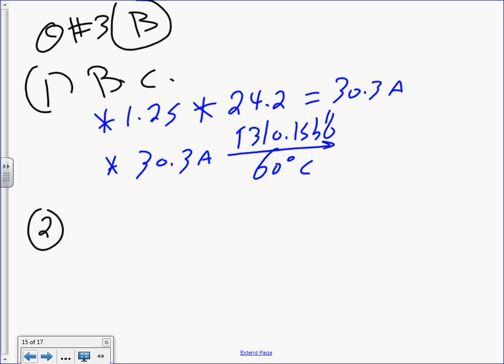The code allows you, guys, if it's 0.3 or less, you can get rid of it. So really, for all practical reasons, since the amps here is very small, this becomes 30 amps. Does that make sense? Because it's less than 0.5. If it's 0.5 or more, you have to go up. Less than 0.5, go down. So this becomes, for all practical reasons, 30 amps, right?